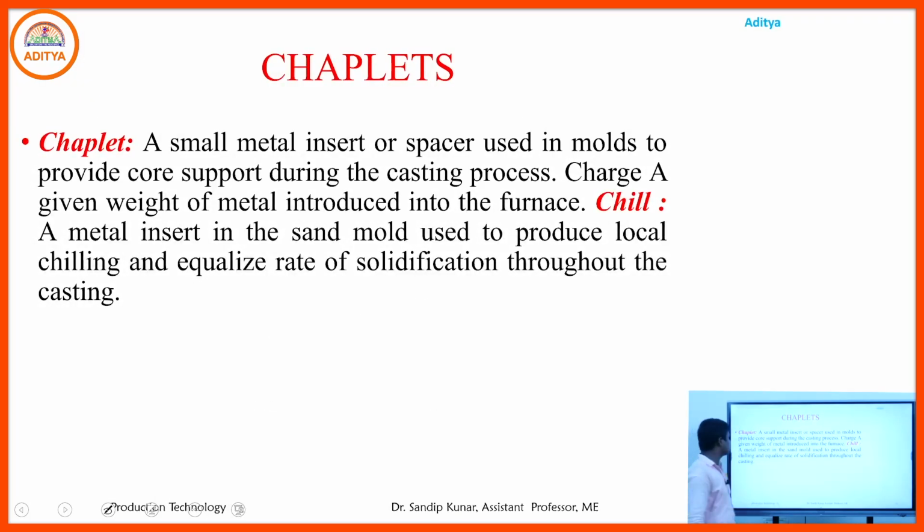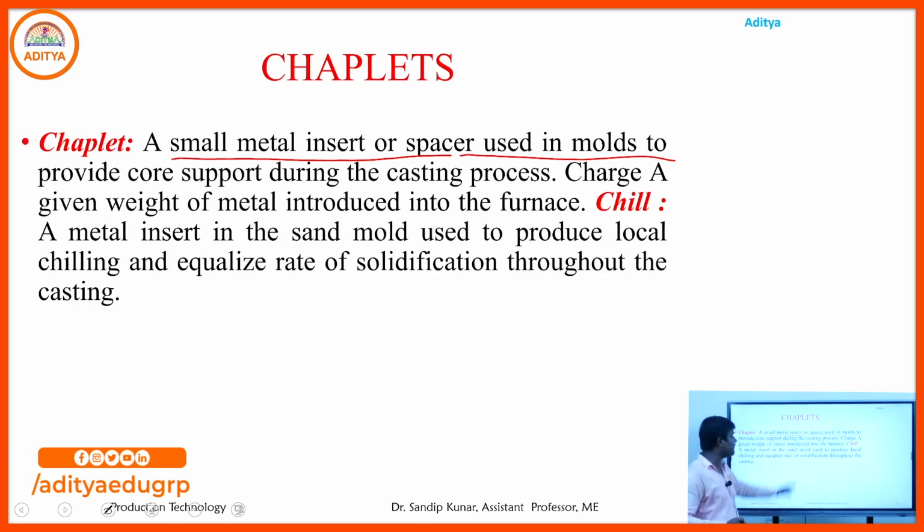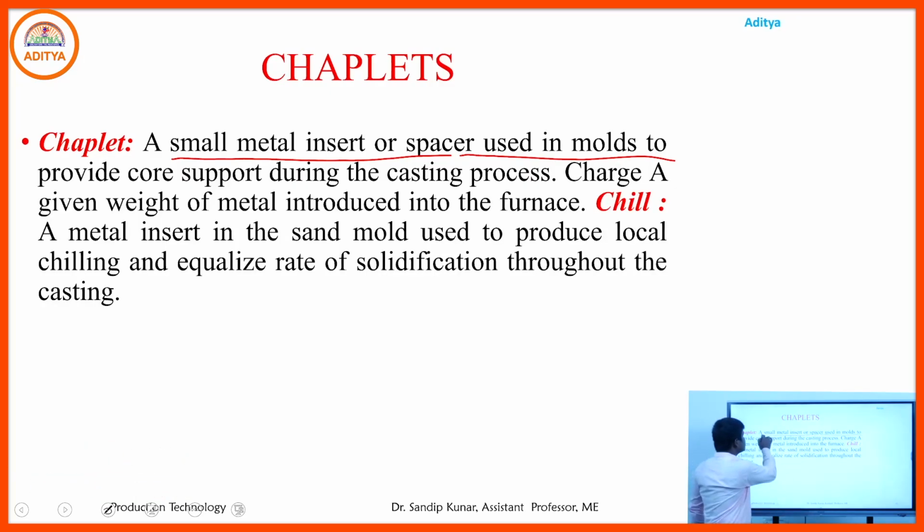Why do we use chaplets? What are they? Small metal inserts or spacers used in molds to provide core support during the casting process. Chaplets will be used for supporting the cores. Small metal inserts or spacers are used in the mold cavity for supporting the core. That is the main use of chaplets.